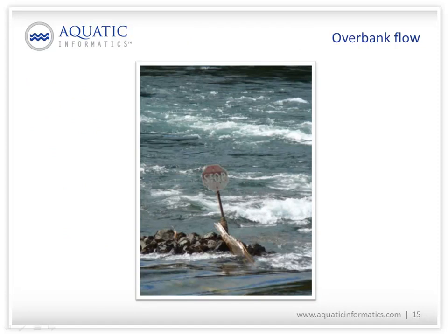There's a number of problems with overbank flow, starting with that. When you get into water flowing through terrestrial vegetation and those sorts of things, a lot of the assumptions we're using in developing our hydraulic relations become somewhat suspect, to say the least. We're generally under-equipped to get the measurements to define the range of stage for overbank flow, to really define what the shape of the curve is.